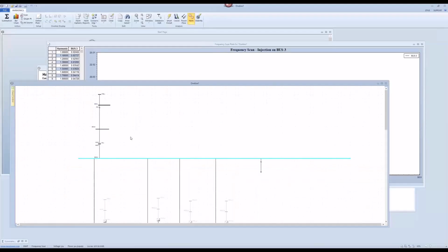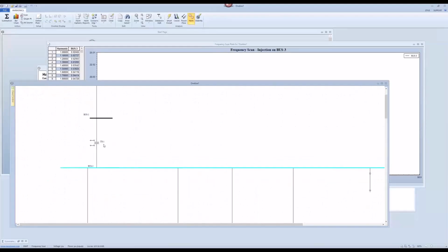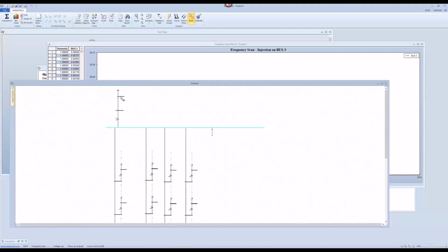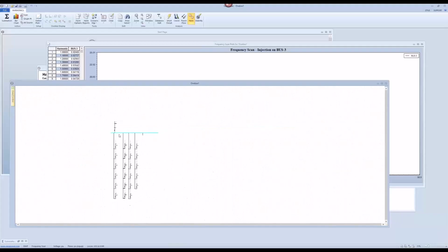So if you only want to know what's my frequency scan result of a transformer, then I can tell you right now it's a linear response, period, because that's the transformer model we have in all of the frequency domain analysis tools, right? So if you apply the frequency scan on this transformer only, then it's just a linear line. If you're talking about the frequency scan, it definitely has to be the whole system. But starting from bus 3, what's my frequency scan result across my whole system, right?